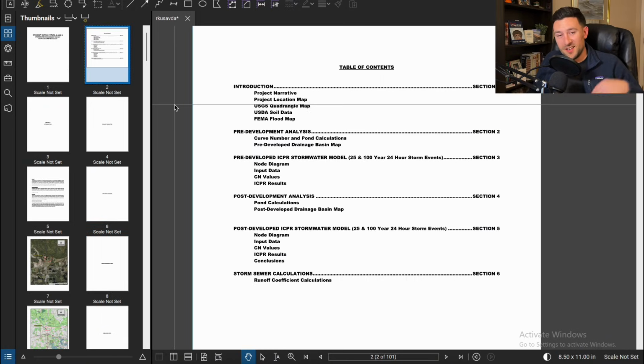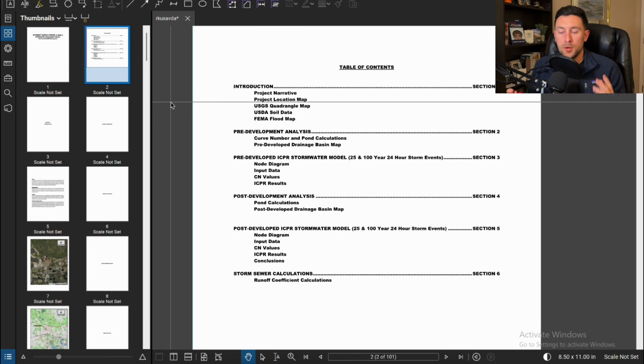All right, I know that was a lot, and maybe some of you actually stuck around, maybe some of you are asleep, but just to kind of summarize this, putting together a stormwater management report is like writing a story. Tell that story of how you're transforming that property into your development. Then you need to clearly explain how you plan to not cause any sort of disturbances to the property or nearby properties through erosion control measures, weir controls. Try not to make your stormwater reports way too long, but also don't gatekeep any secrets in a report. Make it clear, concise, use summary tables, put some page numbers, make your exhibits clear, and tell a good story.